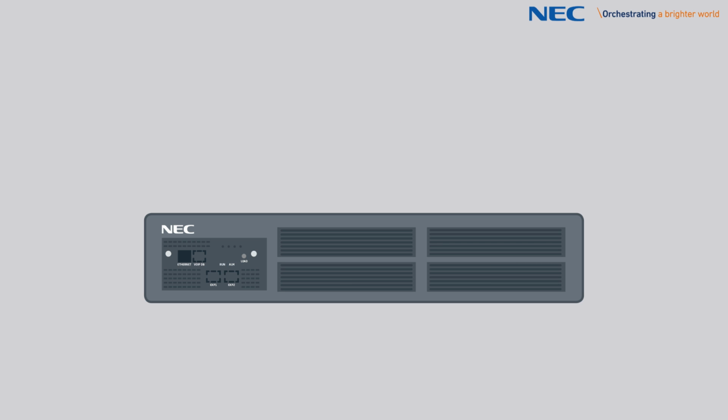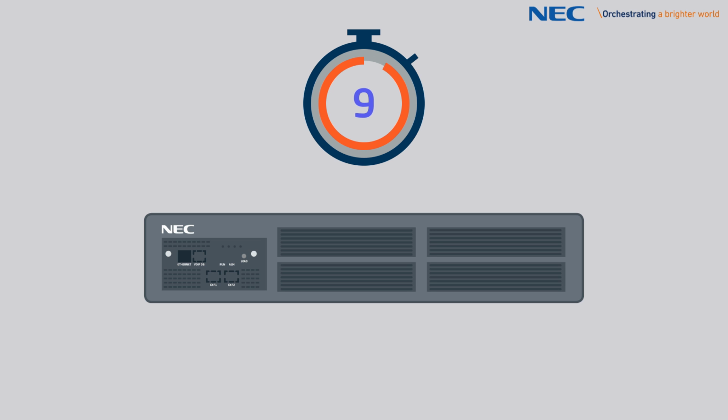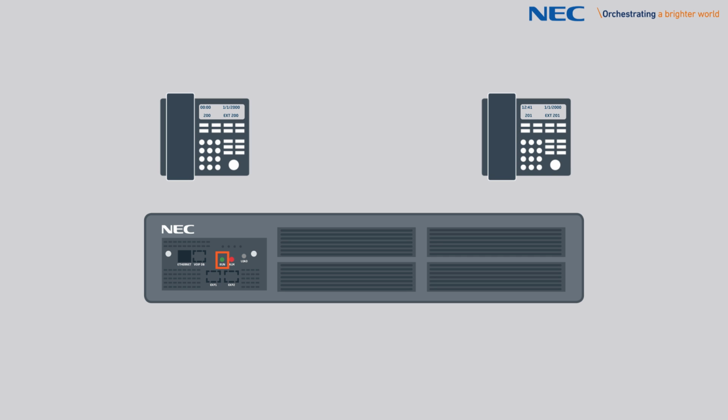To cold start the SL2100, push and hold the Load button located on the front of the CPU card, and turn the power switch on to the main chassis. Continue holding the load button for approximately 10 seconds, or until the ALM lamp on the CPU card lights. Then release the load button. When the system has completed reloading the system software, the Run LED will flash green on the CPU card and the system phones will display the time and date.